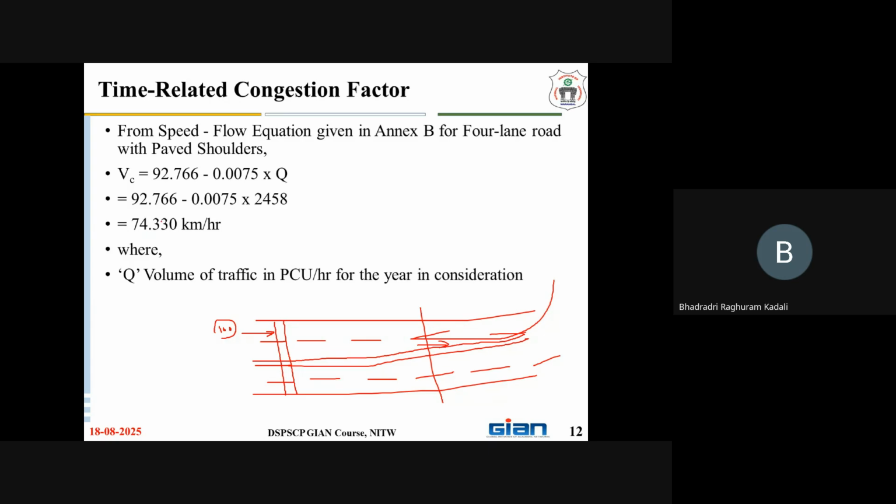So that means the speeds can vary from section to section. At the same time, for volume by capacity, the volumes might be reaching very close to capacity at these blocker sections. So when I take volumes corresponding to densities, or the number of vehicles I'm counting, that might be reaching very close to the capacity side. So it is not easy to rely on only one factor, the speed.